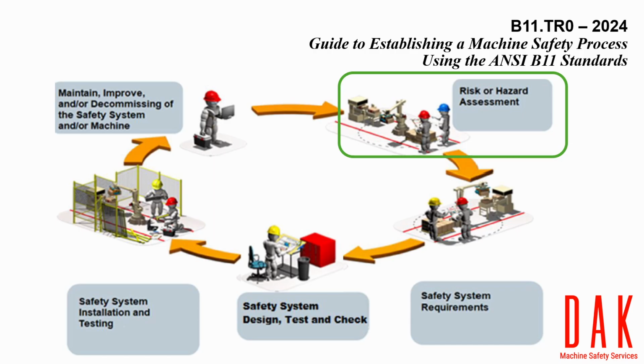During each life cycle phase, machine limits are documented, tasks and hazards are identified, and risk is estimated and evaluated. Tasks may involve any number of reasonably foreseeable interactions with a machine or equipment based on the operation involved. Hazards may be mechanical, electrical, electromagnetic, chemical, radiological, etc., depending on the application. The risks and hazards associated with tasks during the operation and maintenance of a machine should be assessed in accordance with B11.0, Safety of machinery.